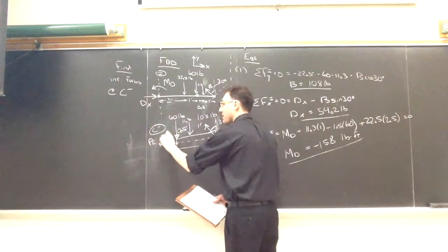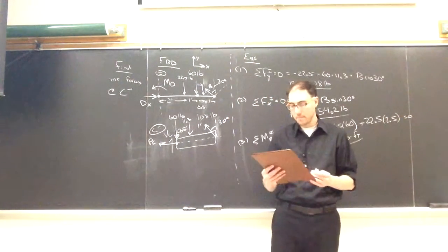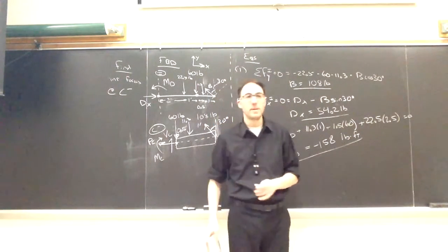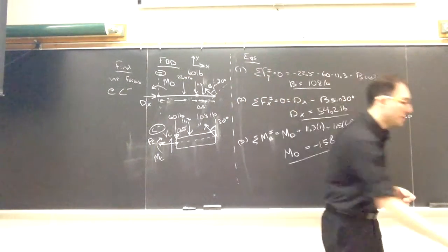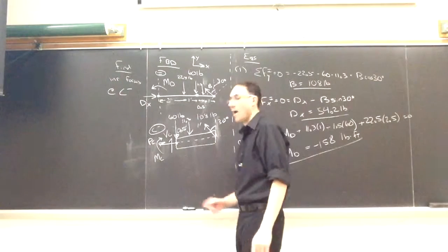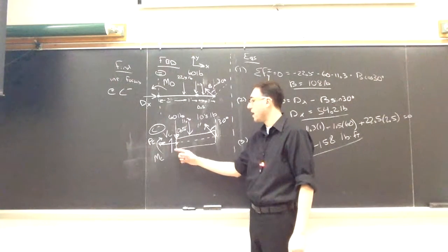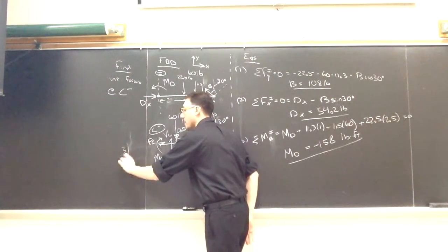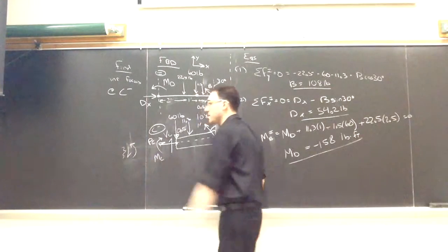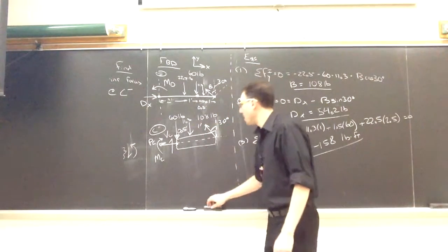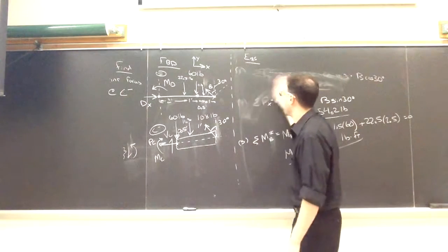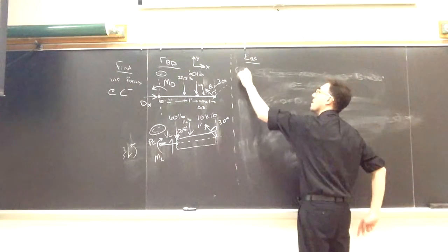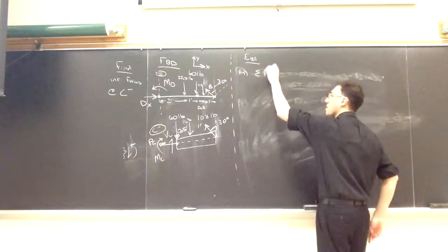I will also have the shear force, I'm assuming up. And the internal bending moment MC, I'm going to assume clockwise since I'm cutting on the left edge of this piece here. So my assumptions are on a left cut that V is up and MC is clockwise. If I kept the other side, I would have made the assumption VC was down and that MC was counterclockwise. All right, so in my internal cut, I've introduced 3 new unknowns, which I can now solve for.